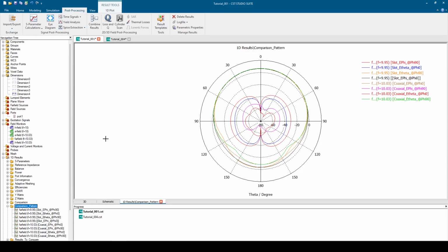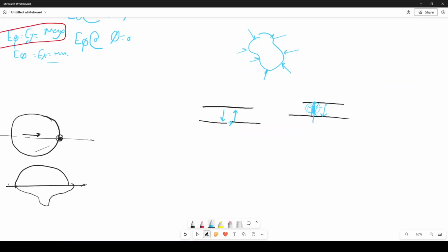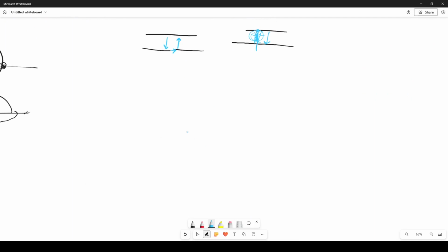So yeah, we can see in the next videos how this can be different, because for example, if we do an antenna array, the fields accumulate, the patterns accumulate. So if I have an antenna element and then I repeat it, and I have any cross coupling that is small, like in dBs, let's say minus 30 dB or something, okay, and then I have many elements, and it depends on the phase in between the elements. For example, the summation of, if this is the coupling, it is very small, but you start to add in phase, it can finally be big, right?